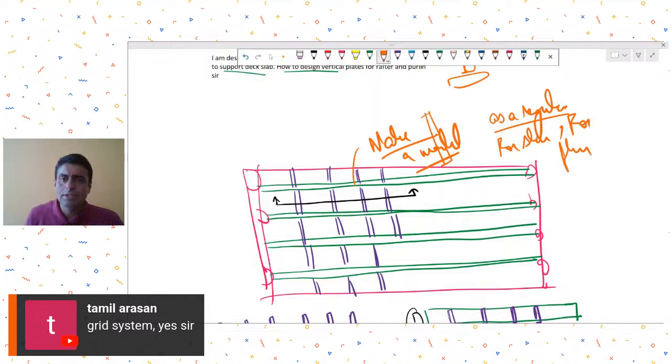This time the only section you have is this, this is your depth, this is your width. Now, only suggestion would be that when you are considering this for flexure, you take it as semi-compact.